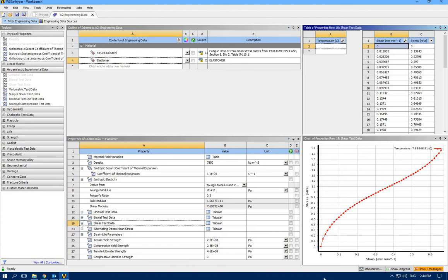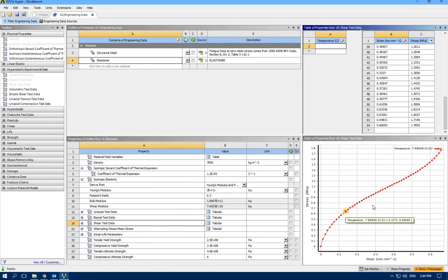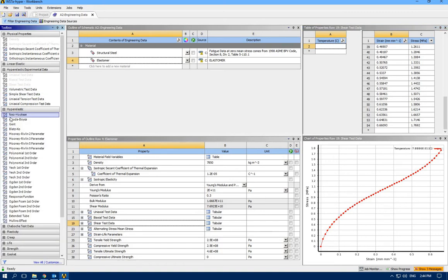Basically, they put all these experimental data in a graph and fit a curve over it. Using that curve, we have data for all points, not just a few points. Here, for example, we may have 54 points. But if you want to use it in ANSYS, it should be continuous information about material properties. So we need to use some models.